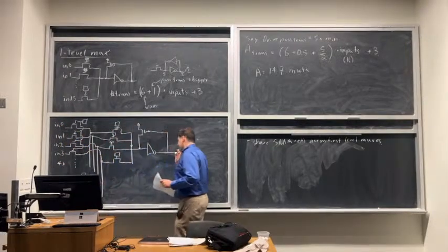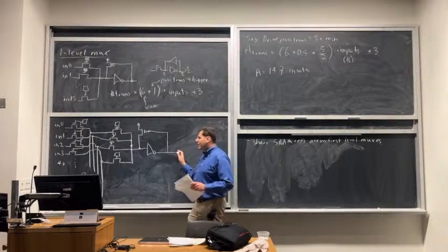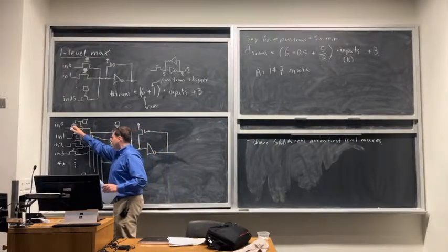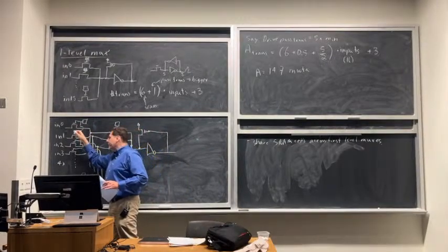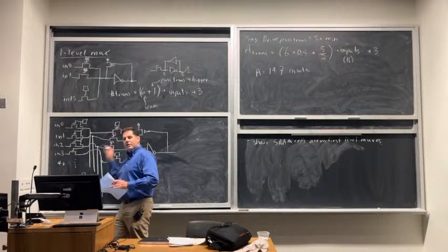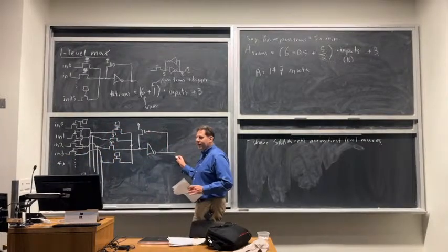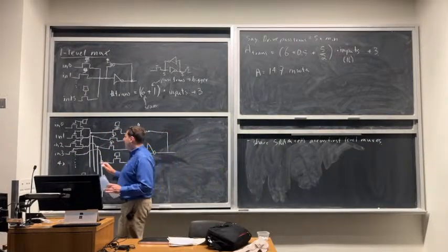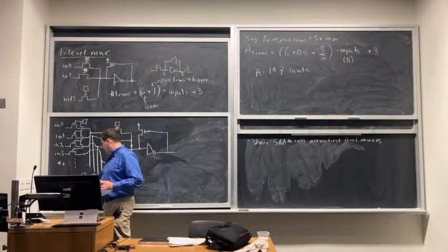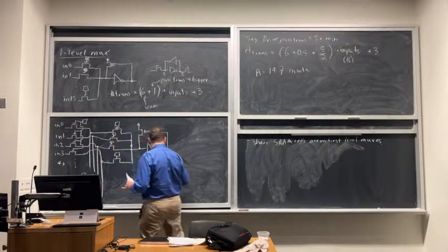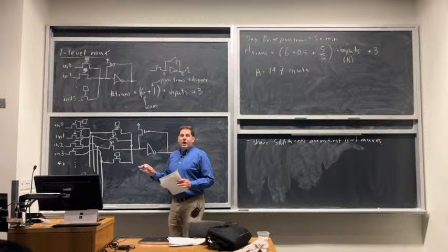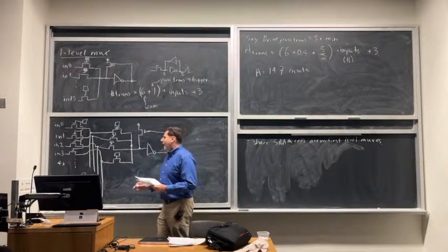This input pin of a lookup table would be a node, and it would have edges for the fact that all 16 of these are legal to connect to this. So the router doesn't care, right? Because it actually can connect any one of these 16 inputs to the lookup table input, no matter how I build this mux.